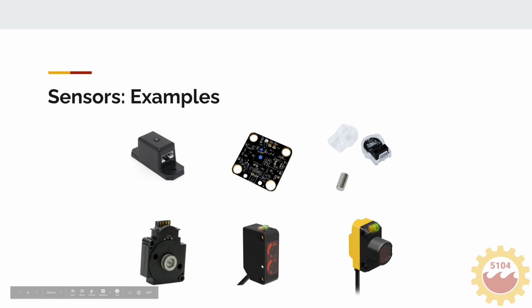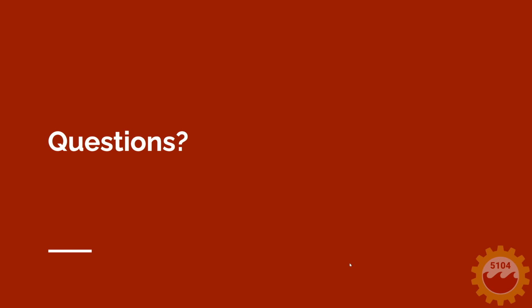This is super useful for detecting things like a hatch panel in 2019. If the hatch panel was just close, it just triggered. Or in 2020, we used it sideways in our hopper to detect when the hopper was full or when it got a ball in to start. This one is a little bit different. We used this in 2019. This shines across, and instead of just automatically coming back at a certain distance, this goes until it hits the retroreflective panel, and then it bounces back, so you can have a little bit longer distance with this and it's adjustable. Okay.